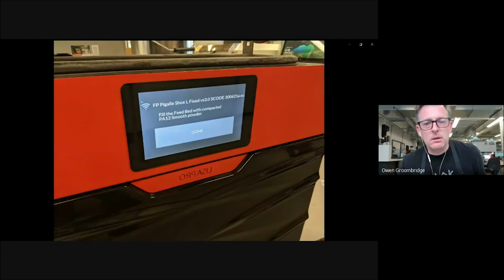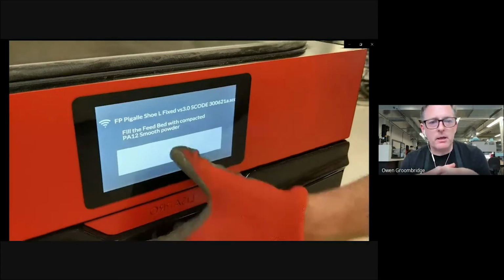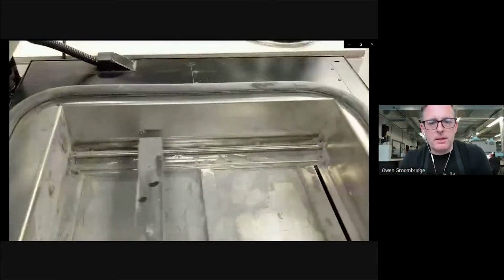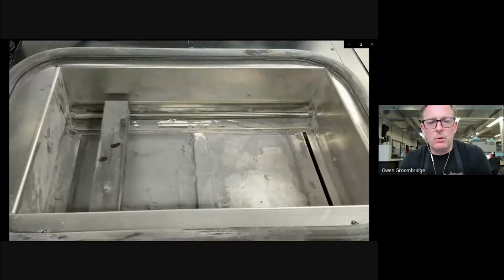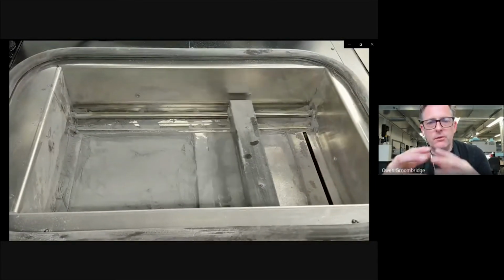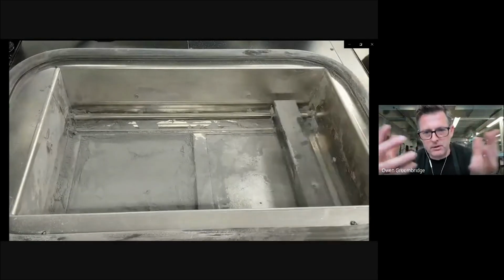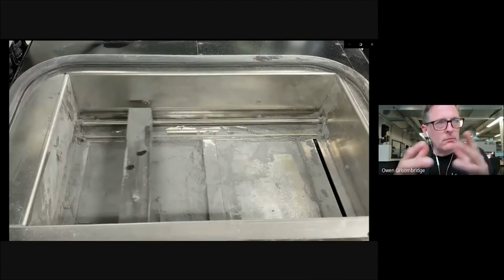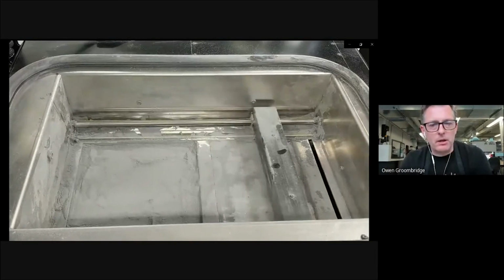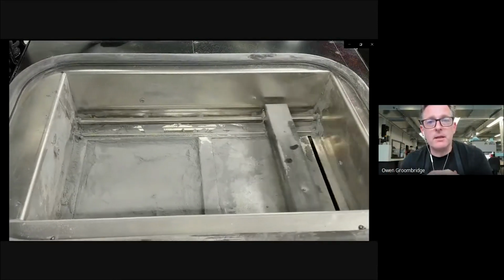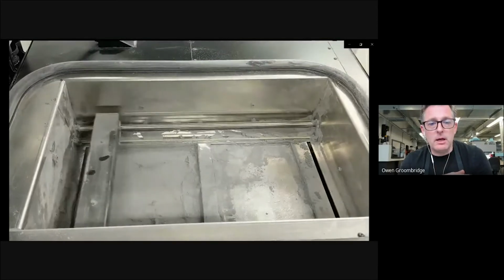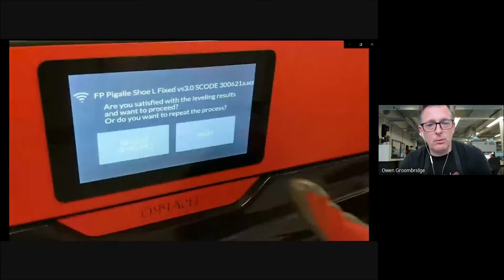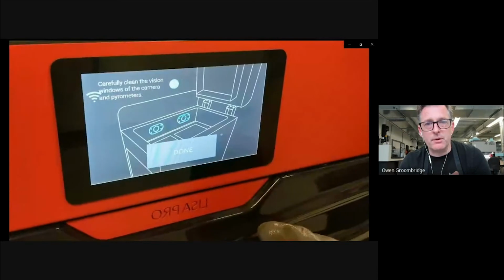Now the thing is, as I said, you can use this powder again and again, but you have to cut it with brand new powder. And the problem is, how do you mix such things? Well, we've got a cleaning device that shakes loose powder off objects that we've already printed. We'll have a look in about 4 minutes on this film, and we can mix the powders that way. If you don't do that, you'll get massive inconsistencies with the print. And this machine hadn't been used for like 14 months up until now, or yesterday, or whenever. And when I come to print something, you can see that later.